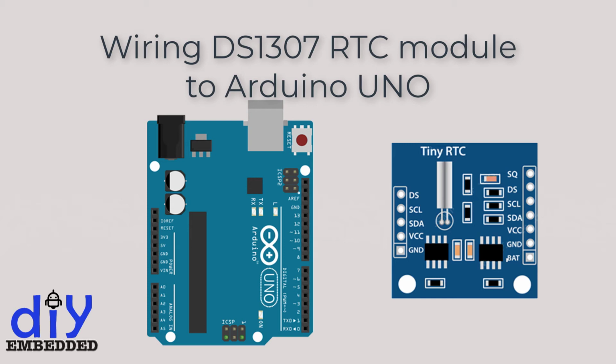Connections are fairly simple. First, connect the VCC pin of the RTC module to the 5V output on the Arduino UNO. Second, connect the ground of the RTC module to the ground pin of the UNO. Now remaining are the I2C communication pins, that is SCL and SDA.